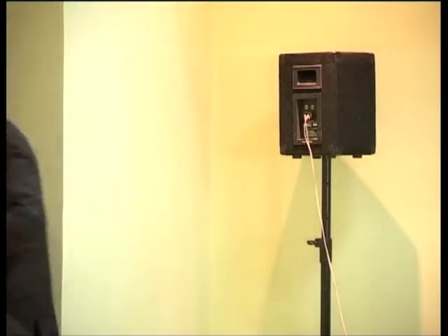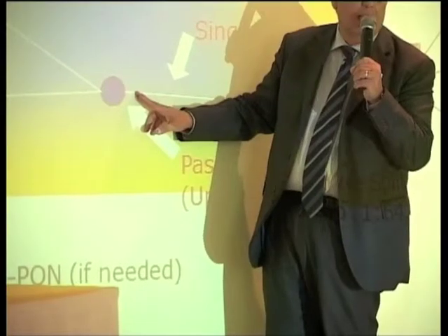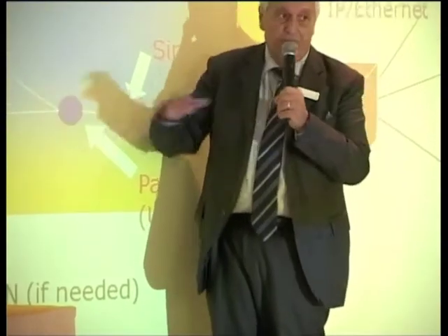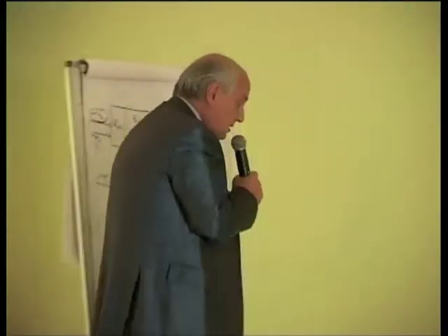So that here, 0 dBm, here you have minus 20 dBm. And since passive optical networks are deployed up to 20 kilometers, you have to add at least other 8 dB for the fiber loss, which makes 28 dB of total loss, which starts to be too much.